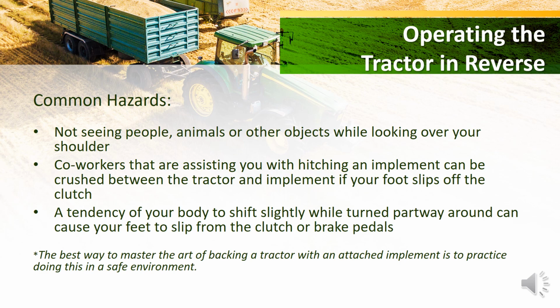So operating your tractor in reverse, there are a few common hazards. You may not see people, animals, and other objects when you're looking over your shoulder. Coworkers that are assisting you with hitching an implement can be crushed between the tractor and the implement if your foot slips off the clutch. And you do have a tendency to shift your body slightly while turned partway around, and that can cause your feet to also slip from the clutch or the brake pedals.